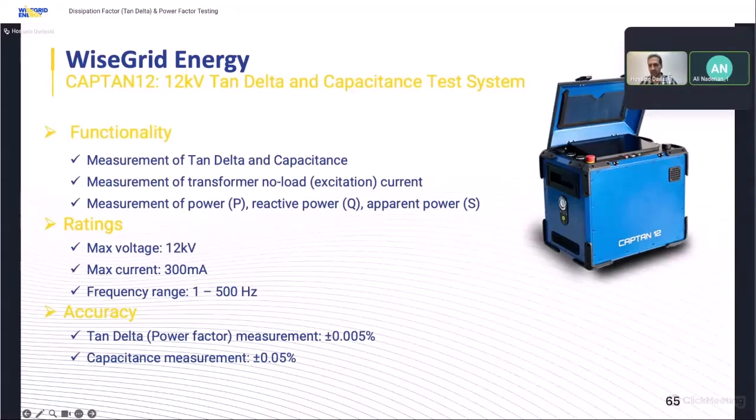Is it necessary to clean the bushing before testing? Yes, I showed a case for voltage sweep. If the bushing outer side is dirty and not clean, we will have wrong values also for C1 dissipation factor, because we have some stray currents from the outer side of the bushing, and it affects our test results. So always please clean the bushing, then wait for it to dry and do your test.